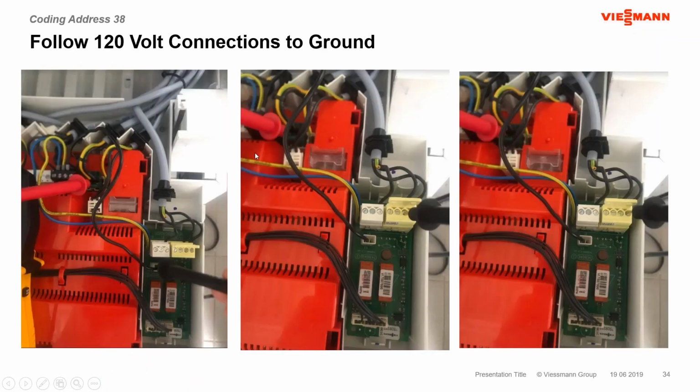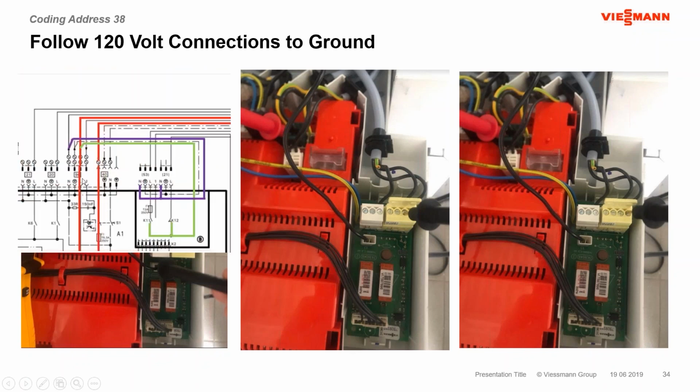The other areas to check on your 120 volt to ground here is we're just checking to see where that power is interrupted, where it came up from the control, but it's not coming back down and hitting that little 1 terminal. We can start checking on the left-hand side here. We're basically checking the power at the 96 plug.